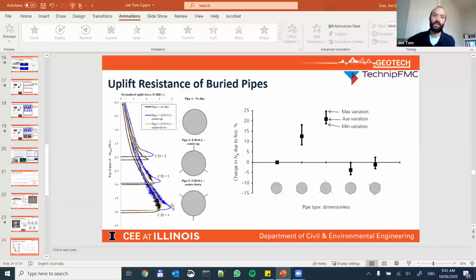So what we've done here is specified the peak, what we think is considered the peak friction and dilation angles for the conditions. And so essentially what we're getting out is just this point. We're just getting out the single point of the peak resistance. So it's what is the peak dilation, what is the peak friction angle, therefore what is the peak resistance of our system.